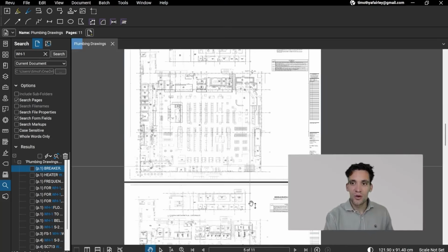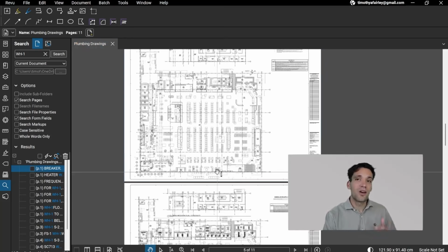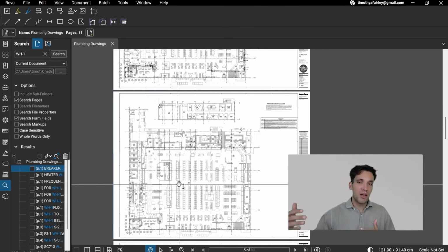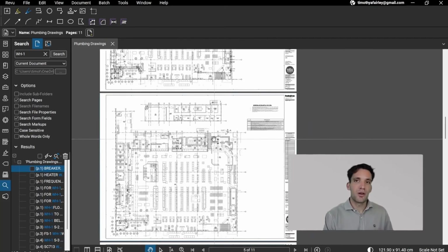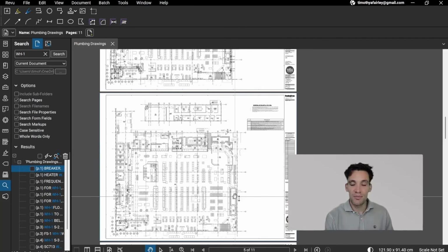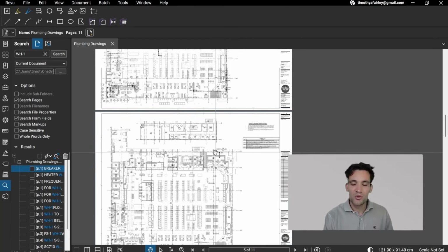And then we're going to then need to work out our assemblies. So an assembly is, if you think of measuring the lineal meters of pipe, what I refer to as a primary quantity. It's something you physically measure on the drawings, but associated with that primary quantity, we'll have a whole list of items to install that. So for example, per lineal meter of pipe, we might need a hanger, we might need some sealant, we might need fixtures to connect the pipe.